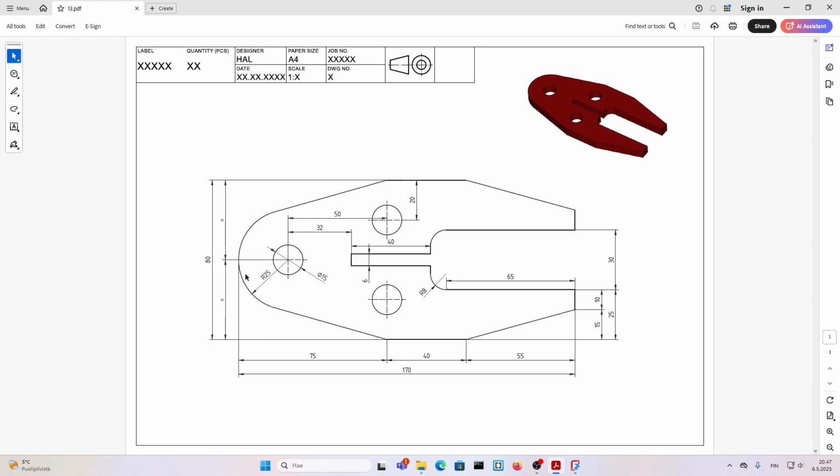That's what I would make first. And then I would use the polyline tool and get the shape of this piece up to here. And then I would mirror this whole thing and get the other section. And in the end, I would just add the constraints to the other side. Okay, so that's how I would do it.